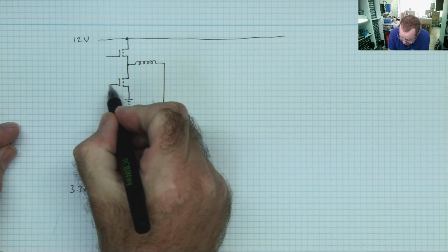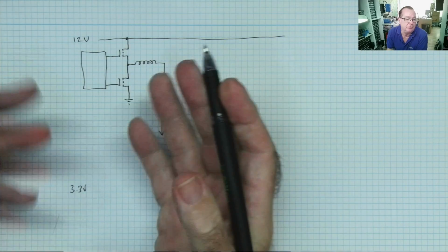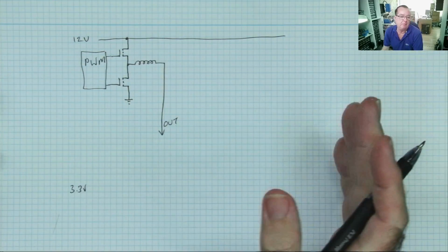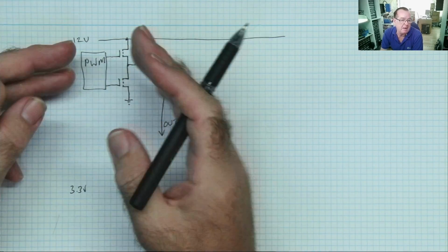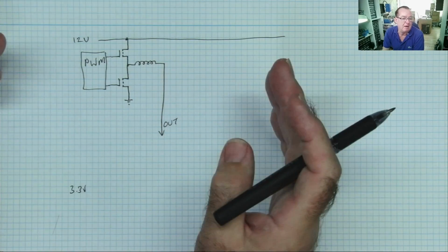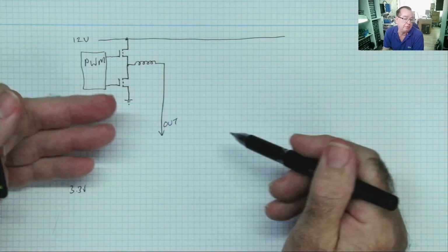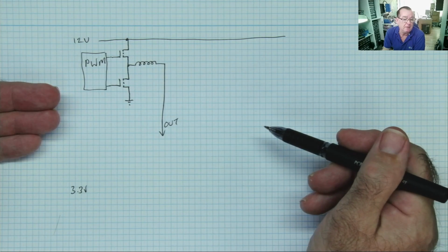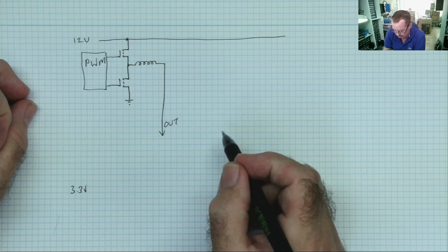These go to a controller. I'll just draw it on one. And this is your VRM controller, sometimes called a PWM, pulse width modulator. Now that is a chip that may be driving one regulator like this, or it may be driving more. So you can have the same chip driving 2 or 3 different voltage rails. Each one of these outs is a voltage rail, okay? So let's just look at the voltage rails we have and what all this means.